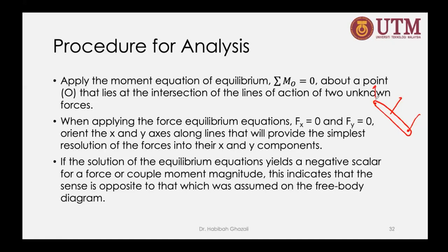So we know a pin support will have x and y. But you can deduce this since you can see that all of the other forces are perpendicular to this member. So you can assign your x and y instead as this. So this is my y prime, x prime. So you can solve it like that.